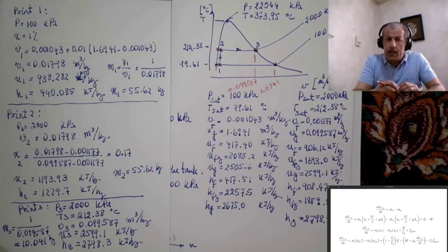It's a closed tank and we just heat it. What does it mean to have a closed tank that we just heat? It means that during this process, neither the volume changes nor the mass changes, and therefore specific volume remains constant. That is a property that we are looking for in the process, and that's what happened in process 1, 2.